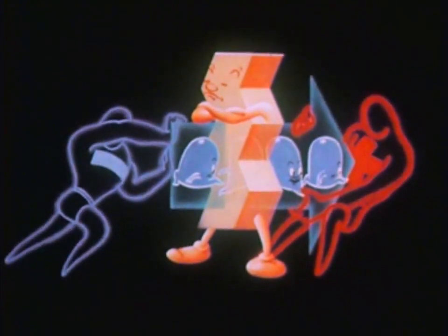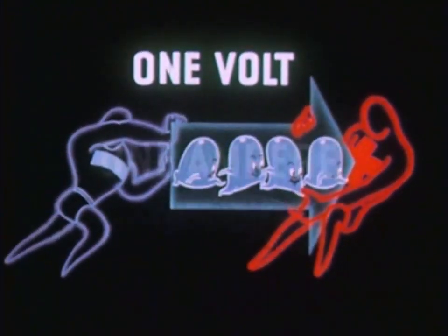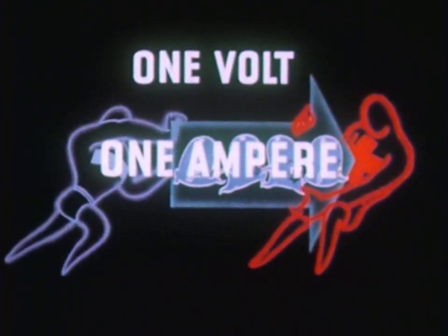The collisions that the electrons have with the atoms set the atoms into more violent vibration. This makes the metal hotter. If there are enough of these collisions, the metal will radiate heat and light. Heat and light from electrical sources, then, can be obtained as the result of resistance in some metals. The unit of resistance is the ohm. Its value is best understood when its relation to the other factors is explained. A pressure of 1 volt produces a current of 1 ampere through a resistance of 1 ohm.